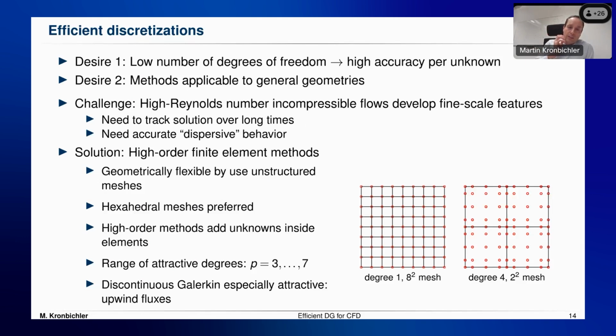Well, it's not really the convergence rate of high order methods that I'm out for, but what I'm out for is actually that the high order methods have very good dispersive behavior, in the sense that they're not distorting my profiles when I consider them over a long time. And of course, if I have high Reynolds numbers, the local structures are small, but they are relevant over a long time when they pass through my computational domain. So eventually, they're going to matter a far distance apart from where they originally were created. This kind of behavior is tracked well with high order methods.